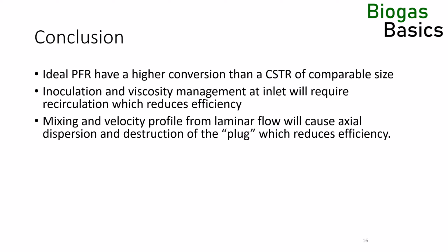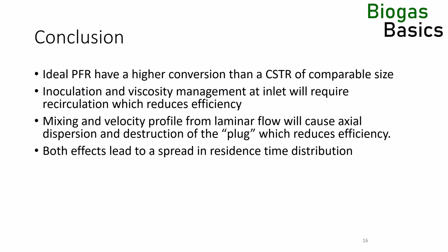Additionally, mixing induces axial dispersion. The combination of recirculation and axial dispersion spreads the residence time distributions. Instead of all feedstock particles spending the same time in the reactor, some particles will leave the reactor much earlier and others much later than the hydraulic residence time. The combined effects also greatly flatten the substrate profile, so the flow reactor behaves more like a CSTR than a